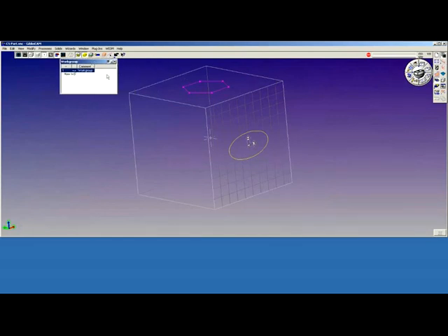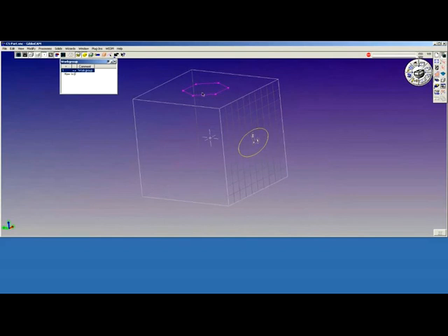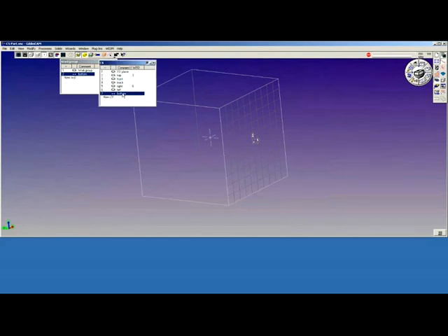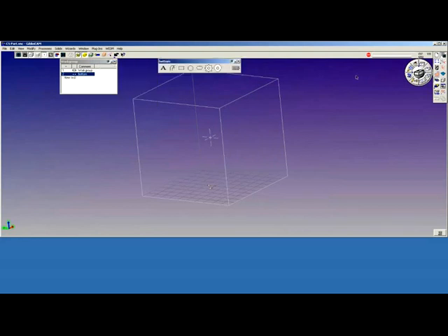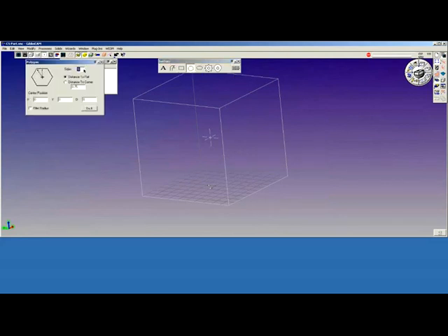For example, work group number 1 contains the geometry for the top and the front. We'll make a new work group and name this bottom. The bottom work group is going to correspond with the bottom CS. In the bottom CS, I'm going to place some geometry, and once again, keep it simple. Let's do a polygon. Let's make it 9 sides, same values. 750 distance to flat, H, Y, and D, 0.